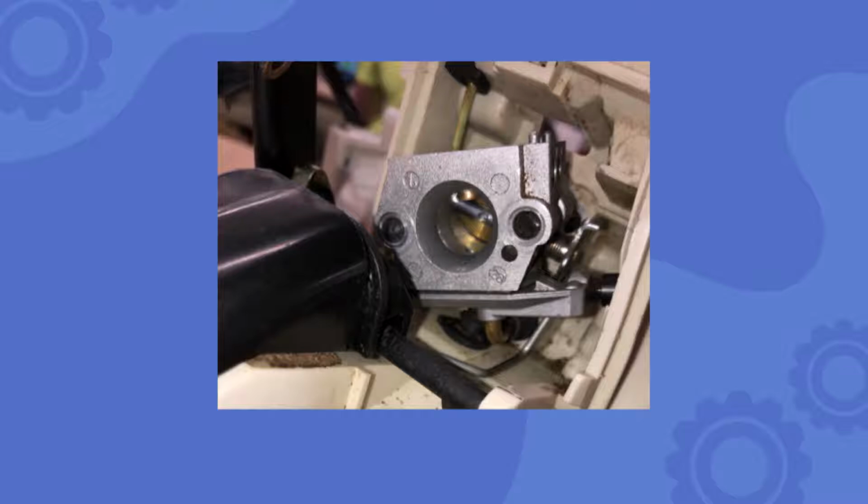The carburetor has a cylindrical body, with a larger outer diameter and a kinked portion with a smaller diameter called a Venturi. The throttle is the butterfly valve that comes after the Venturi. Before we open the butterfly valve to take in air, we use the primer to inject fuel into the engine. We then open the throttle valve.